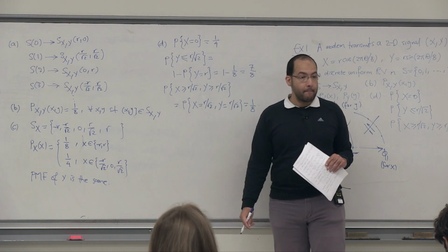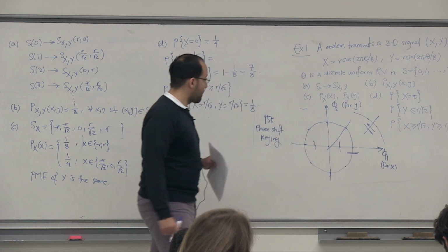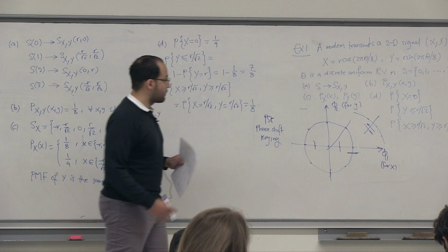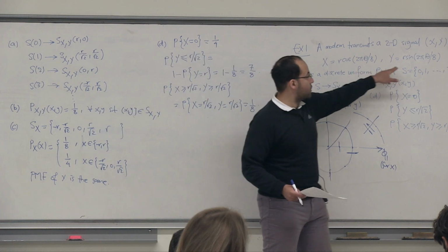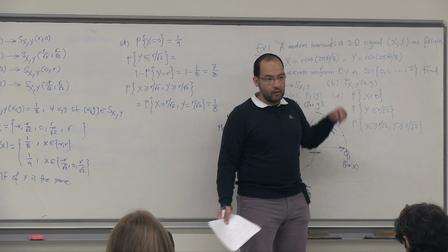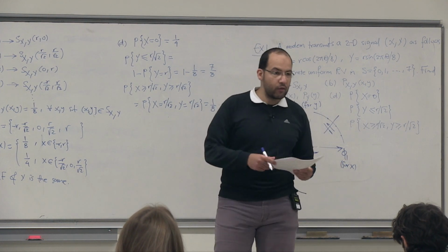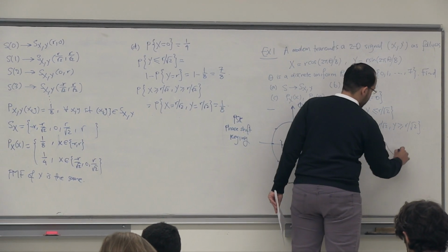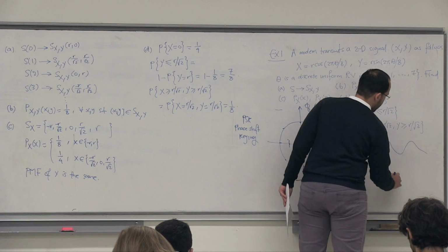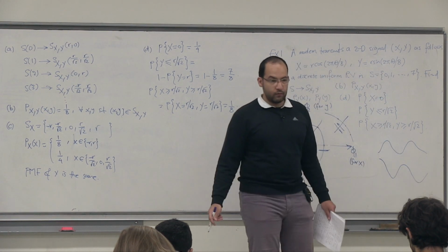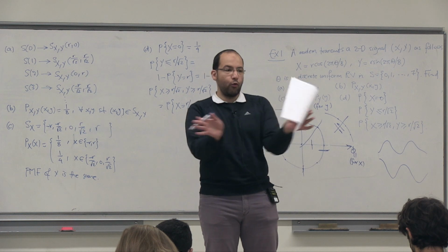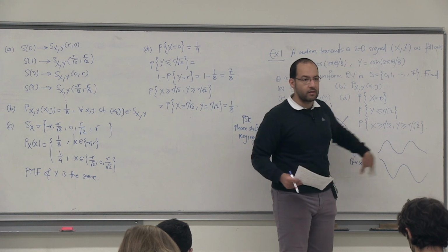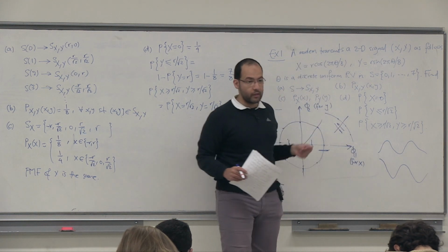Why did you write P1 and P2 instead of X and Y? Why did I write what? P1 and P2 in the problem. Yeah, it is because these are discrete signals, right? We wanted to load them on continuous signals to perform a transmission. In the end, you transmit something like this, right? Either a sine or a cosine. Okay? So we loaded them on orthogonal time domain signals, and these will just determine the magnitude and phase of the constellation point you will put in the space. Okay?